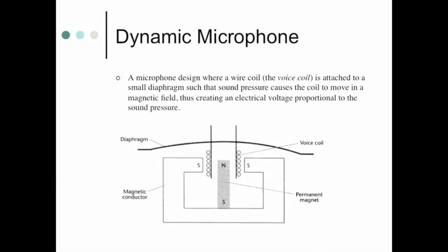So that principle is used in microphone design, and if you look at the picture here, you can see how it's done. You've got your diaphragm here, which is very thin, light, and movable. This is sort of the side view. So this is your diaphragm. And then around the diaphragm are connected some extensions where there's a wire wrapped around. You've got permanent magnets sitting in close proximity. When moving air hits the diaphragm, it makes it move back and forth. And as it does that, the wires move through the magnetic field, and in doing so, it creates some electrical